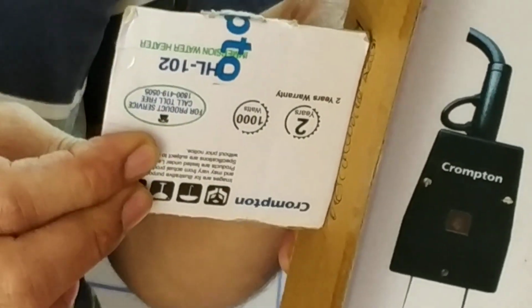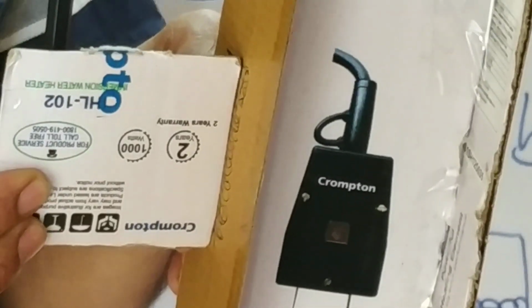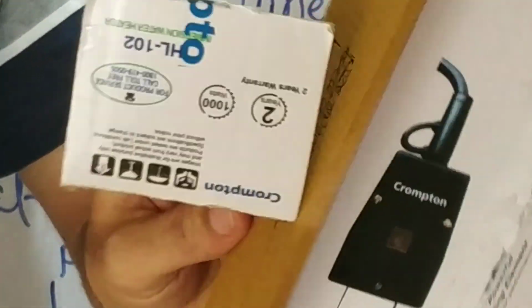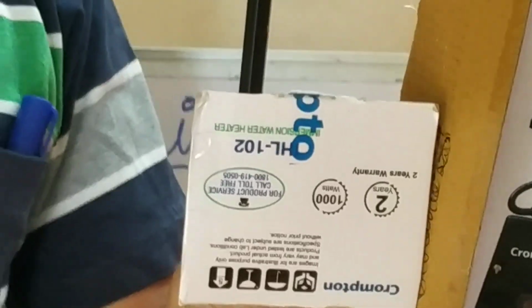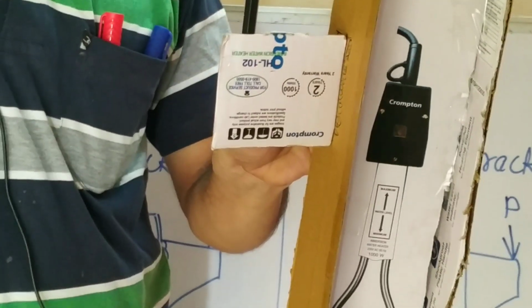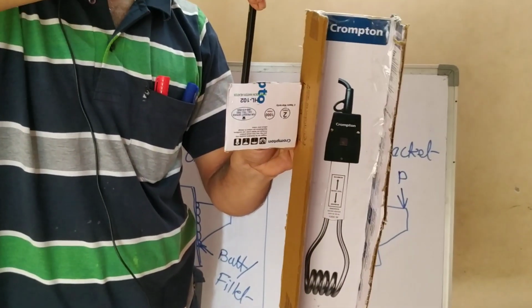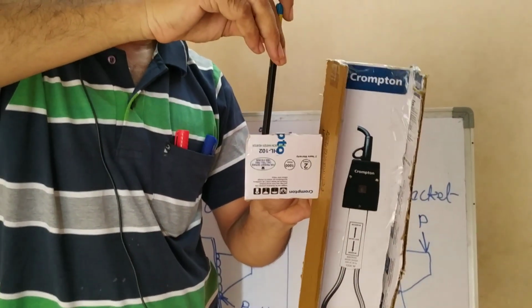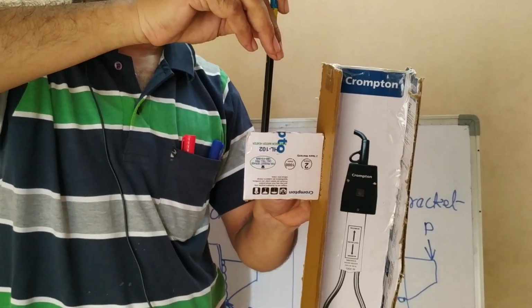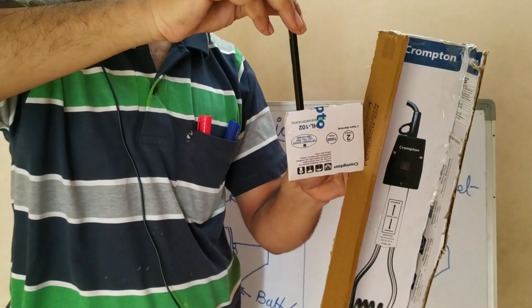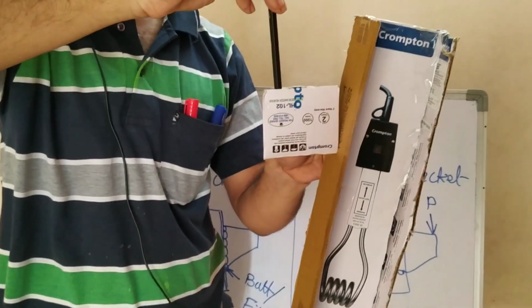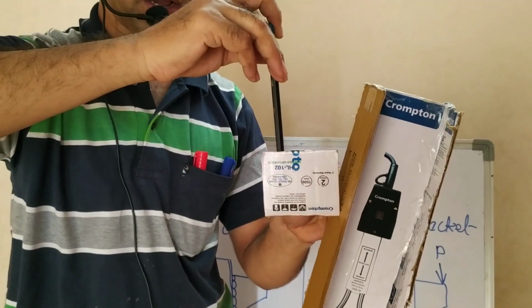If you look at the plane of the flange and the plane of this plate, these two are perpendicular to each other. Now if you carefully observe, due to this load which is coming through my pencil, one, due to the vertical load, the welding is subjected to downward shear, and secondly, due to the eccentric distance, there may be tension at the edge and compression at the other edge due to bending.